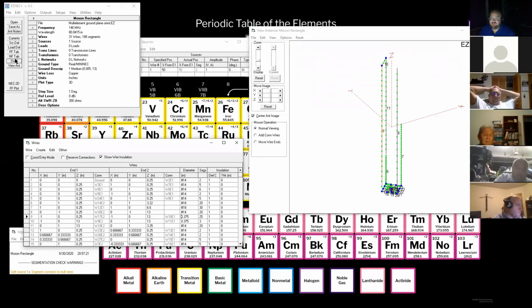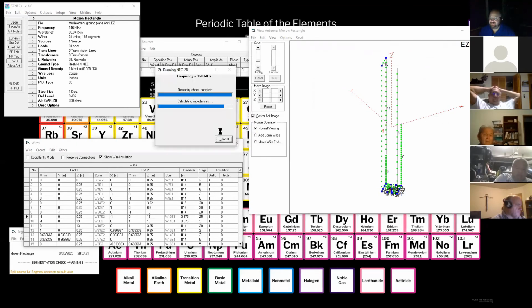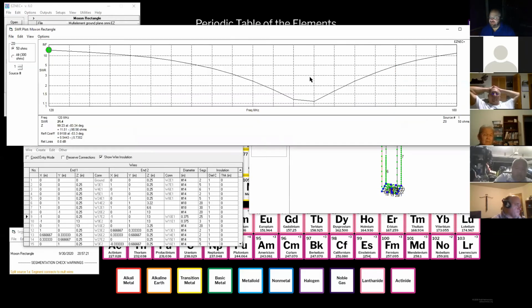And more surface area equated to a better match, because that gave me capacitance that I could then utilize to bring my tune in line. And you can see that I'm still just slightly capacitive or inductive here. I could have gone for a little bit more capacitance, but I didn't want to because my actual impedance is high. So on the diameter, take note about that.